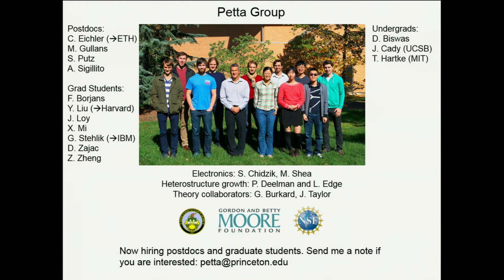Would it be better to have like a phosphorus ion doped into silicon so that we don't have those valley degree of freedom? Yeah, the question is, instead of making these gate-defined quantum dots in silicon germanium, would we be better off using phosphorus-doped silicon, or Steve might raise his hand and say silicon MOS. And I have my own strong opinion about donors.